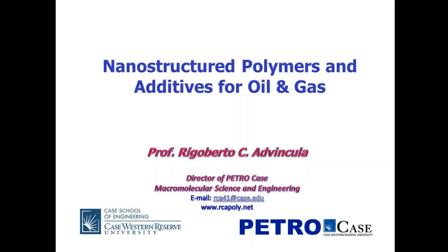So it has to match the viscosity as well as the specific gravity of the fluid carrier. Once it gets into the fracture, then it has to withstand the crushing strength of, let's say, 10 to 20,000 psi, and that means it has to have very high crush strength or compressibility.